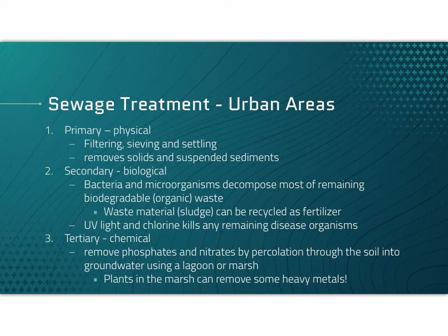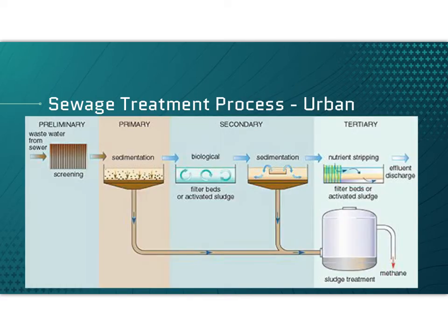Tertiary is where we add chemicals and remove chemicals, depending on what kind of wastes we are treating. In tertiary, we are removing phosphates and nitrates. Again, remember, those are not good for our water supply. This is done by percolating them through the soil into the groundwater using a lagoon or a marsh. Plants in the marsh can even remove some heavy metals. So it's just a different way of filtering and removing particles.